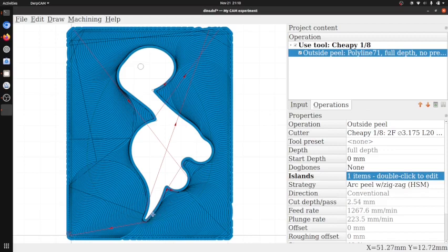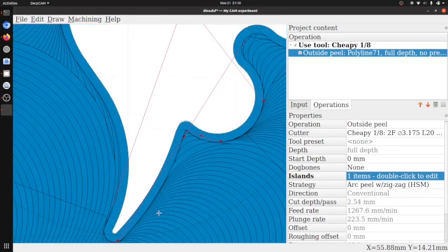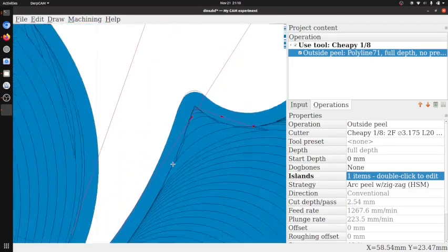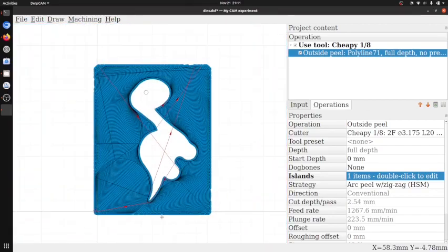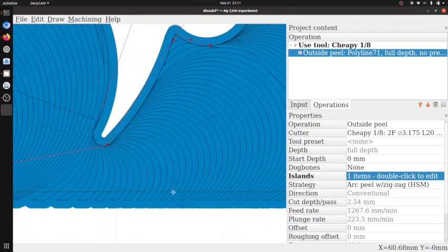You notice the edge of the arc at the dinosaur is doing the same thing I mentioned earlier. It's coinciding with the edge of the shape at a very shallow angle, sort of like relieving tool pressure. Actually, on the edge of the material, it doesn't matter. This is the edge of the material. It really doesn't matter what it does here. It can afford to just run off the material, in whatever way is most time efficient.